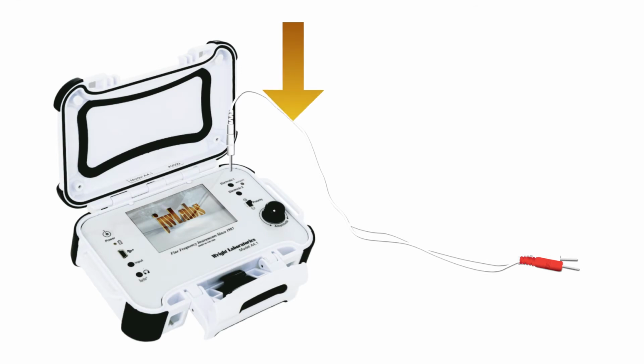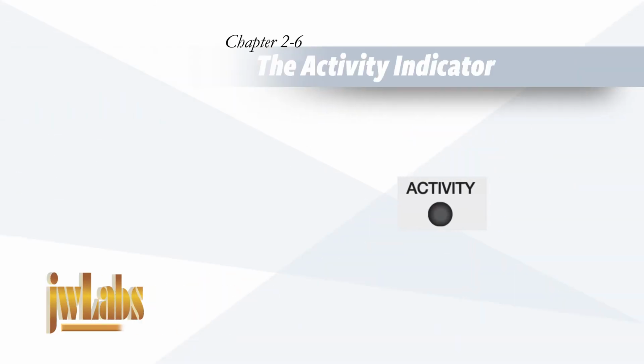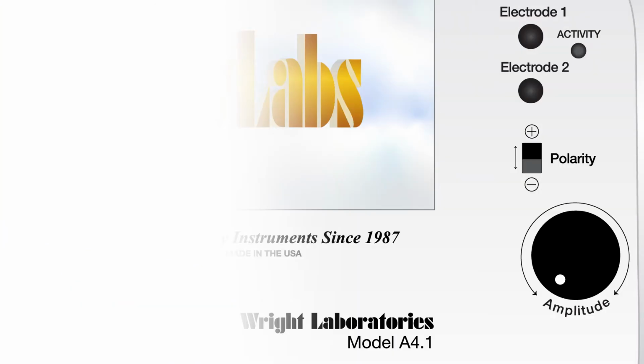Make sure to insert them in a straight downward motion and don't apply pressure when inserting or removing the electrode wires, as this can damage the ports. Activity indicator. When there is output and the electrode wires are active, this LED will glow green. This means there is current moving through the wires.